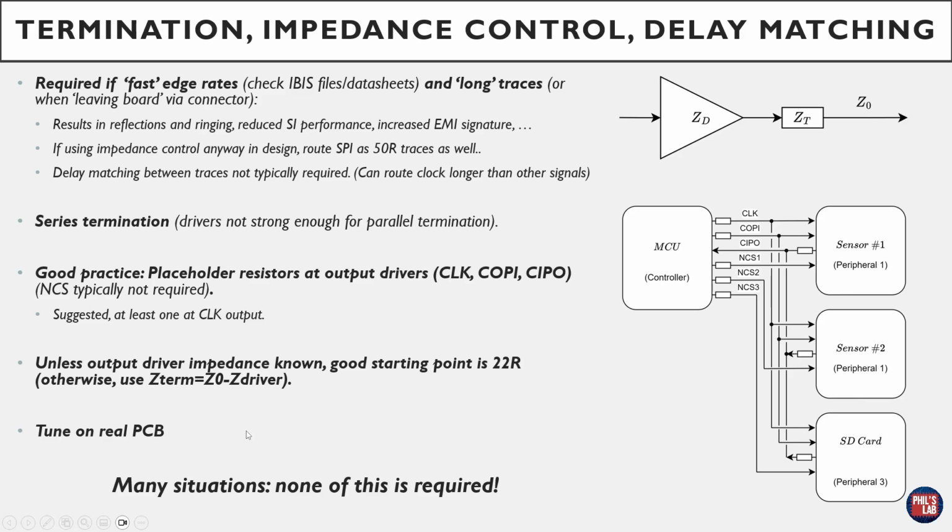Again, this is something you need to tune and measure on the real PCB, see if there's any ringing, any reflections on the signal lines, and if they are causing issues, that could be data issues or could be EMI issues, you can increase the value of those placeholder termination resistors. So if you have them in the design, it's much easier to tune them than to respin a board and add them in later. Again, in many situations, none of this is actually required.